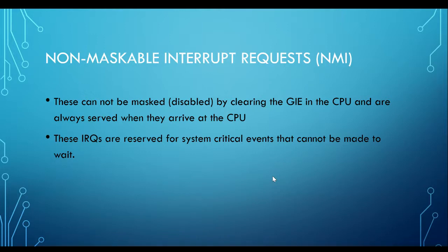But what about those non-maskable interrupts? Now it's very important. Why must we have interrupts that cannot be masked? Okay, a lot of reasons. Power, brownout, power issues. You're plugging a 12 volt supply into the embedded system. Suddenly there is a dip. Okay, it can actually spoil the embedded system, a dip from 12 volts suddenly to 2 volts. What can be done? Okay, nothing.